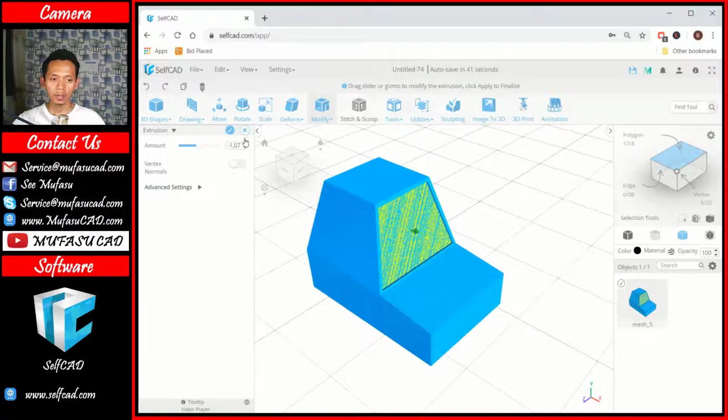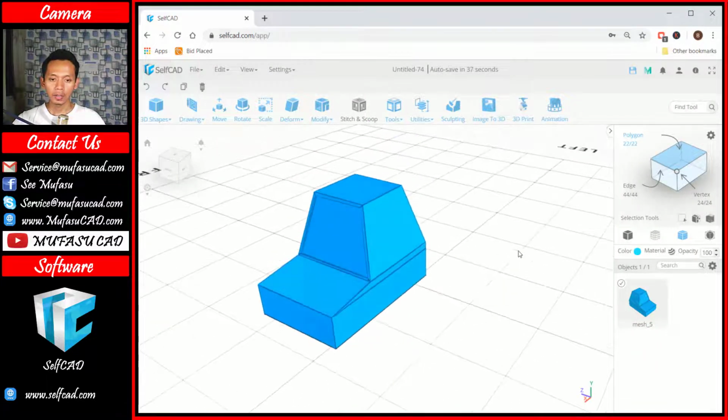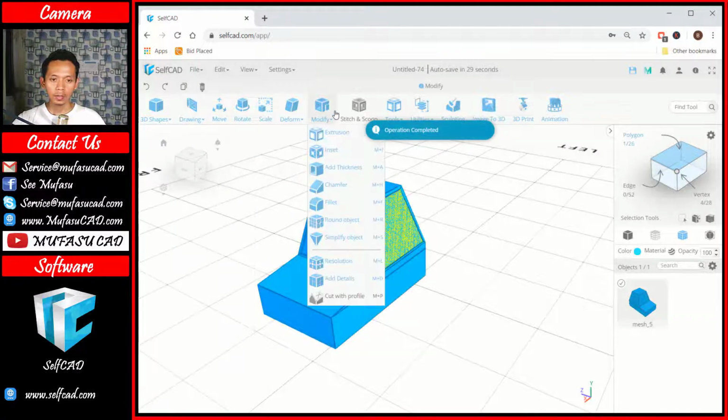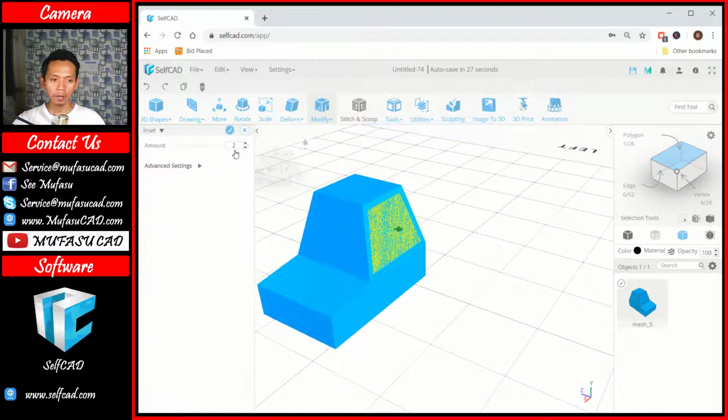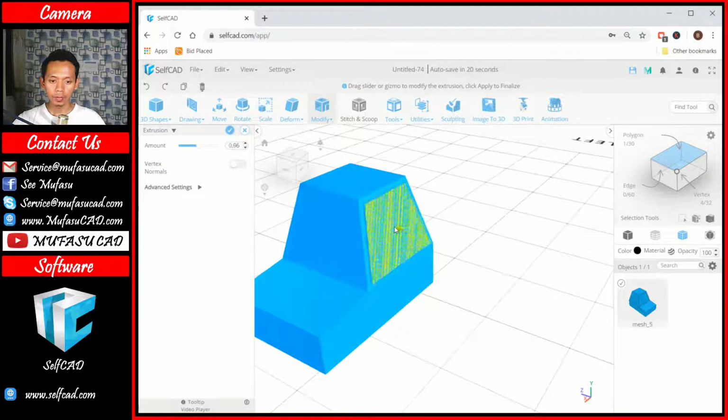And the next you can click OK. Now we can select again this face. We can use the insert command. We set amount 2. And next we can use insert again, amount 1. The last we use extrusion. We extrude into this point.